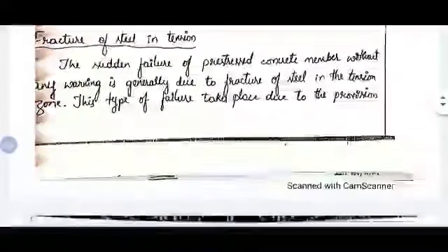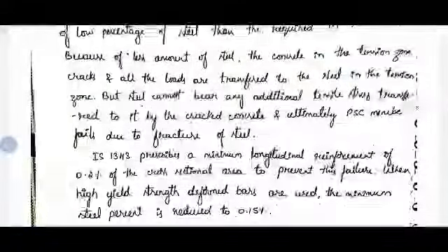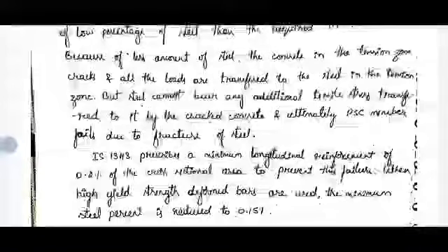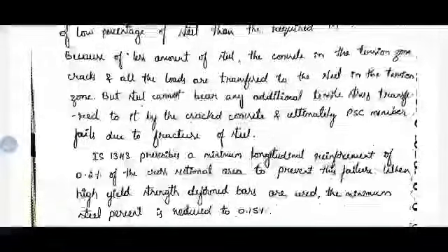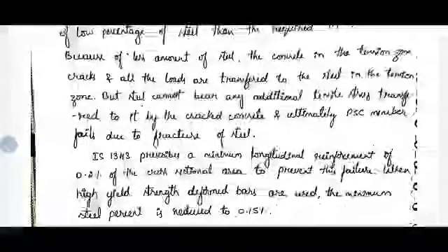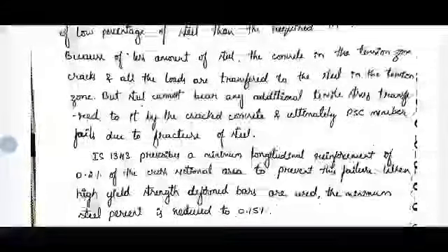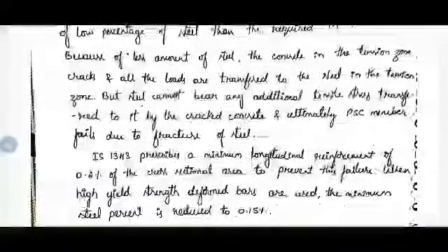So in that case, when the beam gets deflection, the concrete gets cracked and it will transfer the tensile stresses developed in the concrete to the steel which you have provided, but it is not able to carry the loads or the stresses, so suddenly it breaks down. That breakdown we call fracture. Because of that fracture, the beam will collapse. That is the fracture of steel in tension due to excess tensile stresses developed or transferred from concrete to steel.